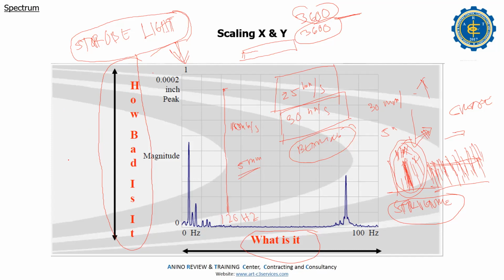You know you have the RPM. The hertz is 25 hertz, I think. Yeah, 25 maybe. You divide by 4. There's a spectrum for the vertical pump. Example, the RPM is 3,600 divided by 4. I divide by 60. 3,600 divided by 60. That is 1x, right? Divide by 4. 15 hertz. There is 1x, 15 hertz. I experienced this one.